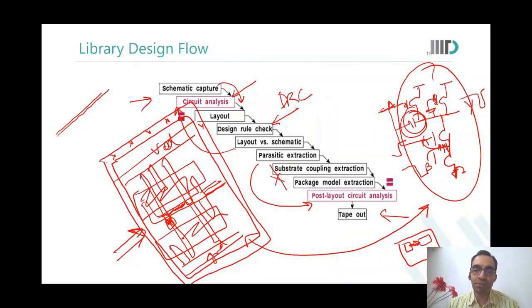Akash is asking this in the chat window also. What do you do? I said you increase the size of your NMOS and your PMOS so that it can now sink more current. Yes, sir. When you increase the size of your NMOS and PMOS, what does it do? It increases the drive capability of these devices. So they can now sink or provide more current. So that extra current can discharge this extra capacitor also within the stipulated time. That is why you will come back within the specifications. Okay, sir. I understand. Akash, does that solve your problem?